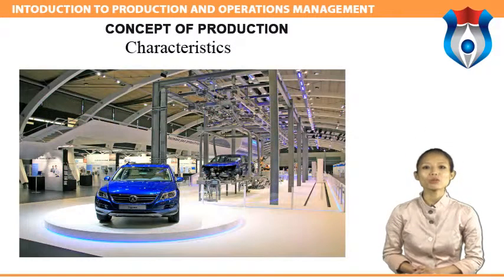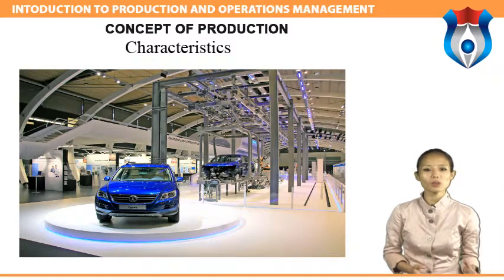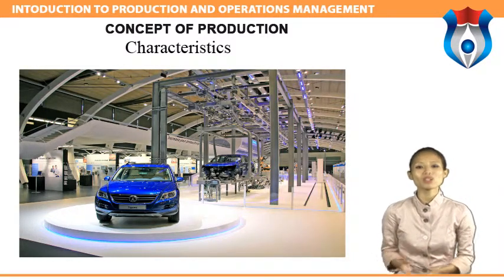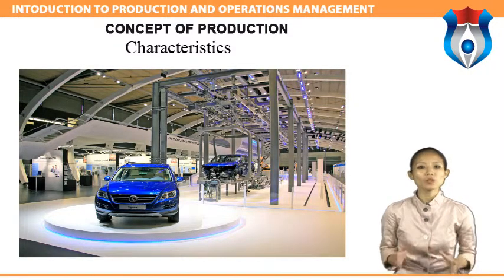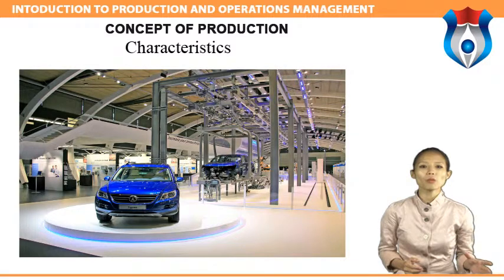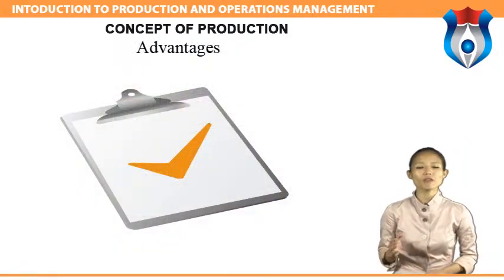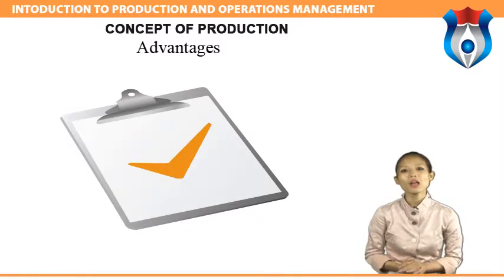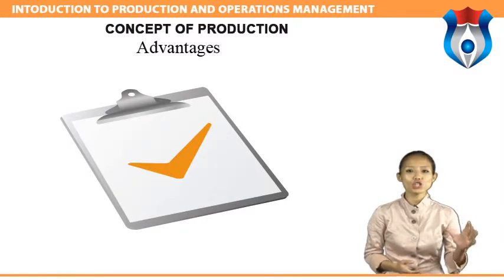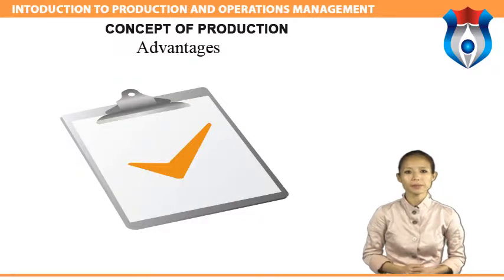Mass production is used under the following circumstances: standardization of product and process sequence, dedicated special purpose machines having higher production capacities and output rates, large volume of products, shorter cycle time of production, lower in-process inventory, perfectly balanced production lines. The advantages of mass production are: higher rate of production with reduced cycle time, higher capacity utilization due to line balancing, less skilled operators are required.